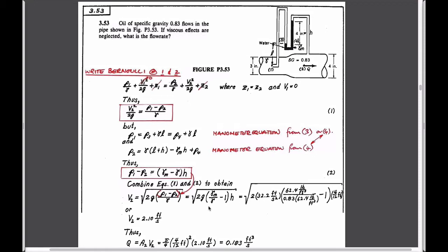You could measure things with a pressure transducer. You can also measure them with manometry, with a gauge fluid in the system. This is basically the same application as before, trying to measure velocities directly. Obviously, instead of having this arrangement here with a manometer tube which is looking upstream, you could also have a manometer tube that was just cut off horizontally, in which case it would measure the pressure between these 2 points.